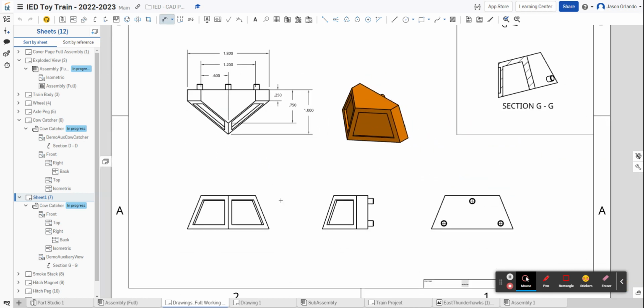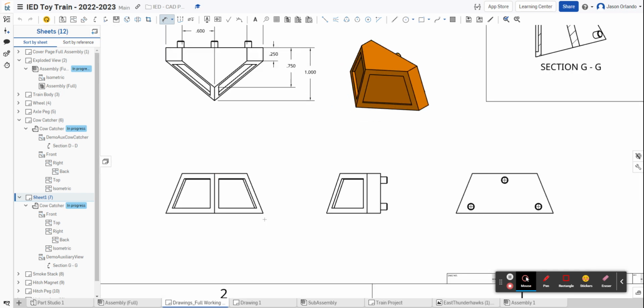All right, I just pressed D to turn dimension on again, and now I'm going to go from the bottom to the top and give that vertical dimension. So if I were to sketch those two pentagons on planes that are 0.75 apart, that's how I will loft to them.